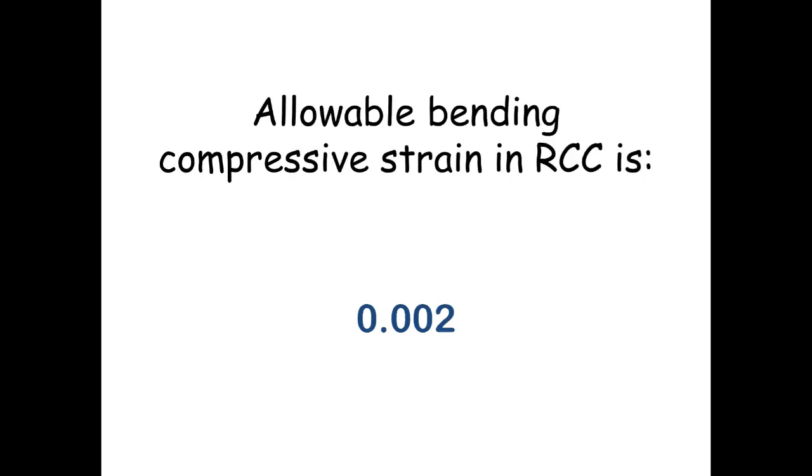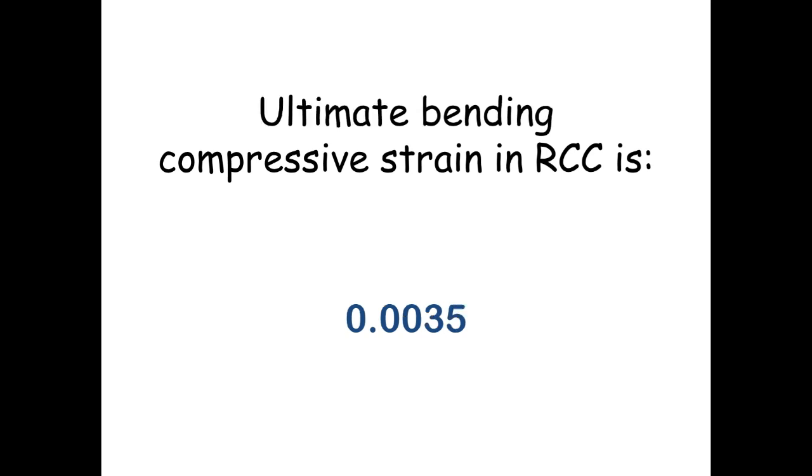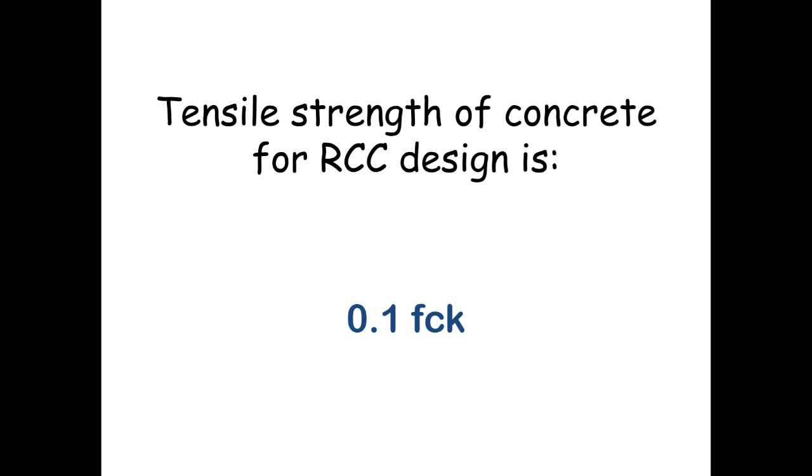Allowable bending compressive strain in RCC is 0.002. Ultimate bending compressive strain in RCC is 0.0035. Tensile strength of concrete for RCC design is 0.1 FCK.